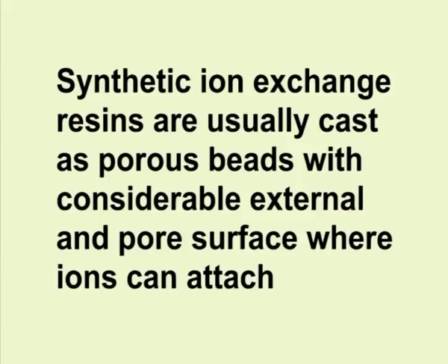An ion exchange resin is a polymer, normally polystyrene, with electrically charged sites at which one ion may replace another. Synthetic ion exchange resins are usually cast as porous beds with considerable external and pore surface where ions can attach. Whenever there is a great surface area, adsorption plays a role.